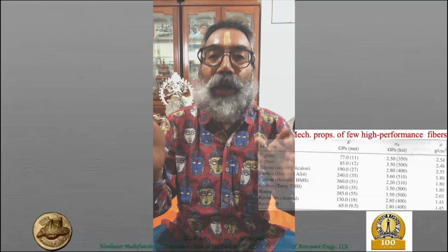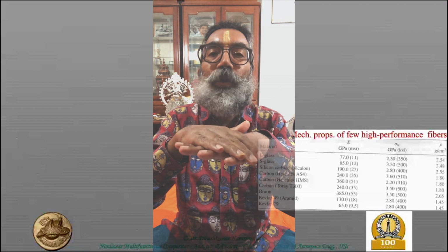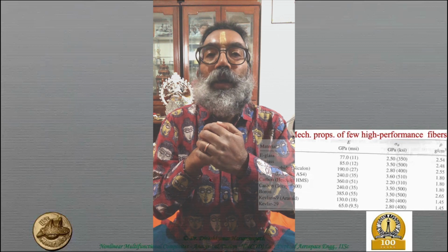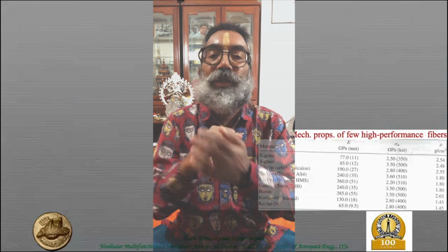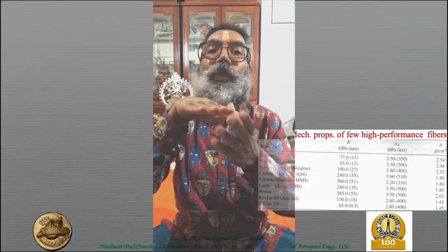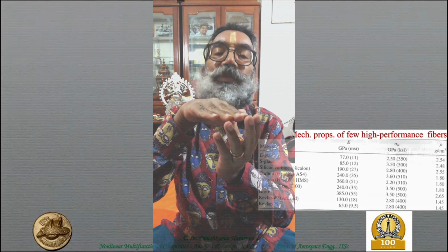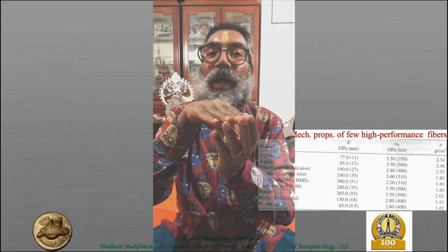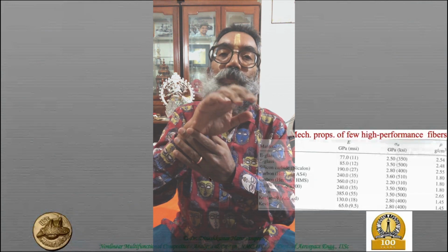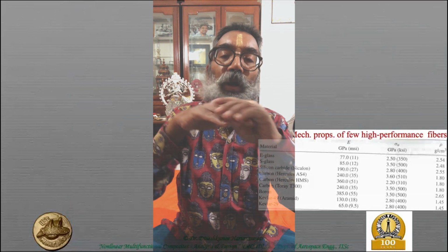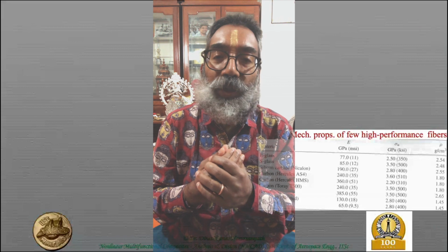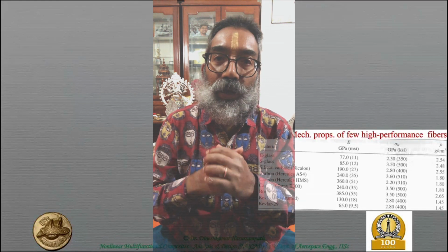And of course, the other thing is that it's not just fibers alone we are talking about. The matrix is also there. So the matrix offers substantial compressive strength over and above what the fiber itself does. And once the fiber is within the matrix, because it is held in place, now it has a certain amount of compressive strength that it can offer as well, in addition to that of the fiber itself. But the fiber by itself has very, very poor compressive strength, because it's not being held in place. That is the primary reason why its performance in compression is so poor when it is separate.